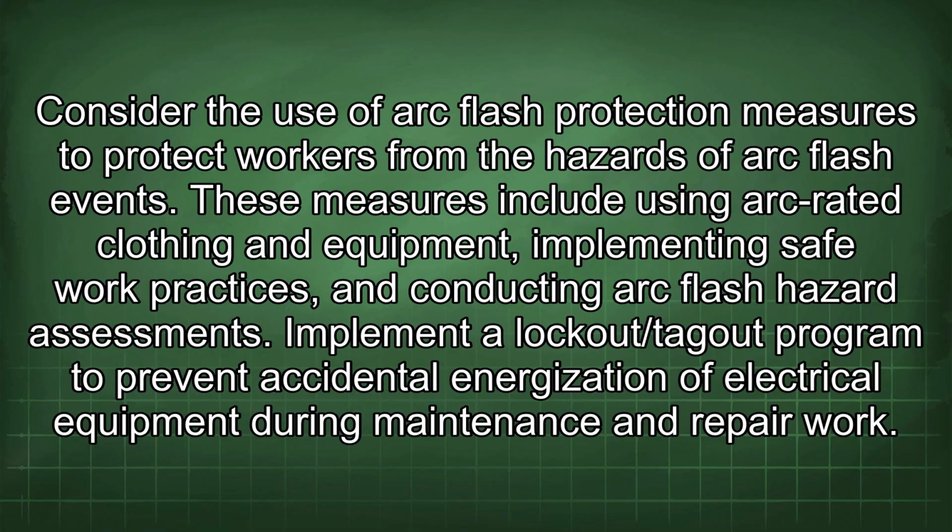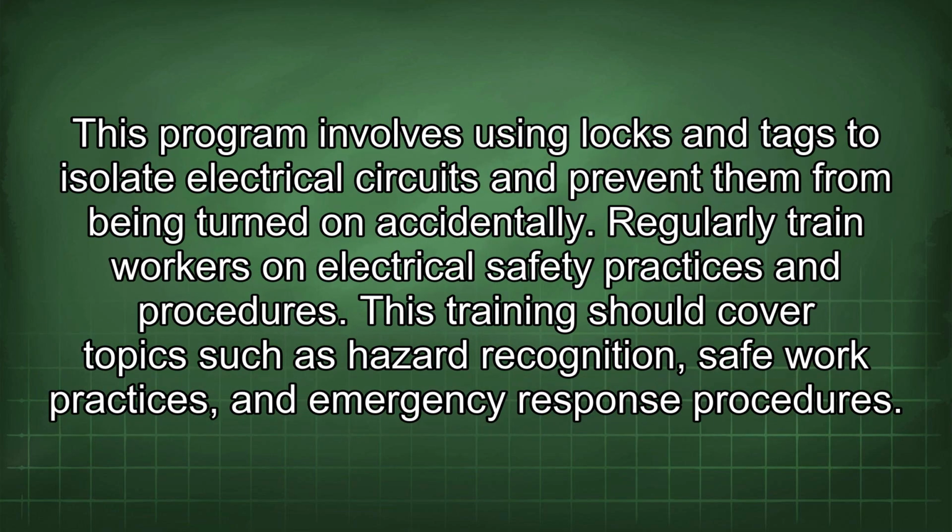Implement a lockout/tagout program to prevent accidental energization of electrical equipment during maintenance and repair work. This program involves using locks and tags to isolate electrical circuits and prevent them from being turned on accidentally. Regularly train workers on electrical safety practices and procedures. This training should cover topics such as hazard recognition, safe work practices, and emergency response procedures.